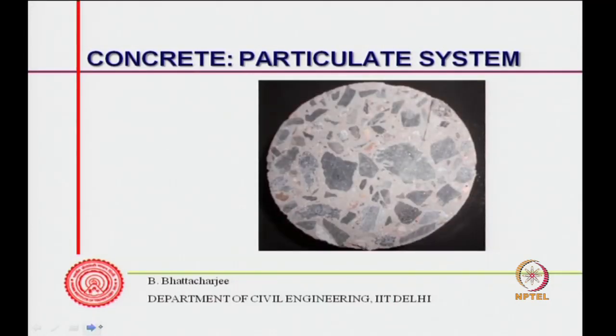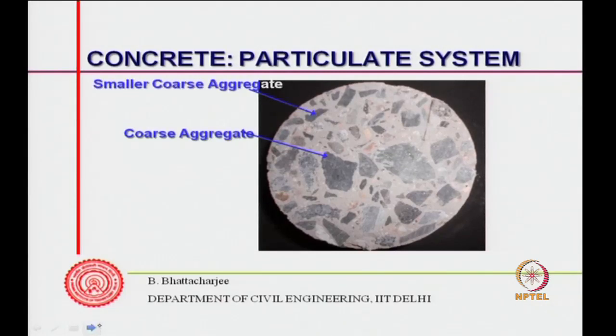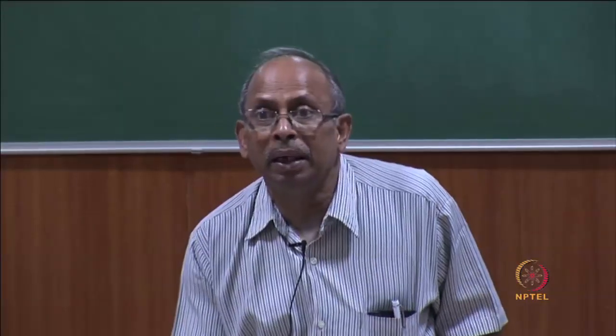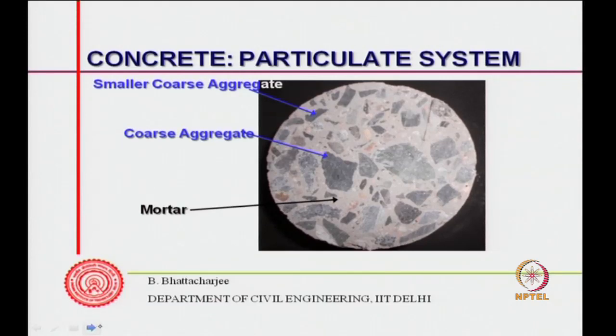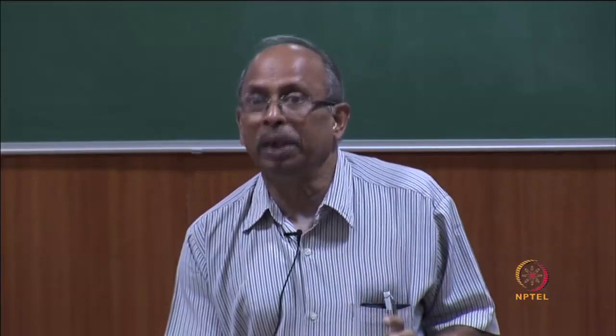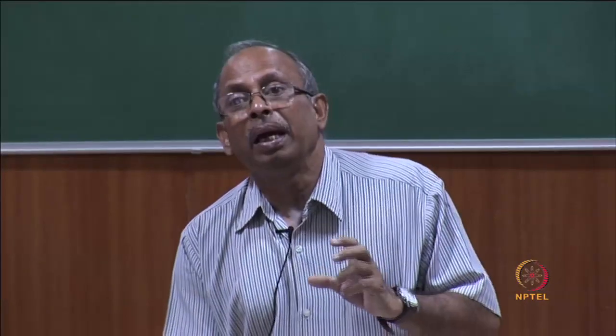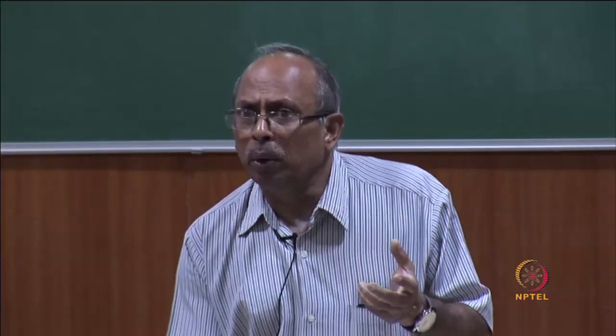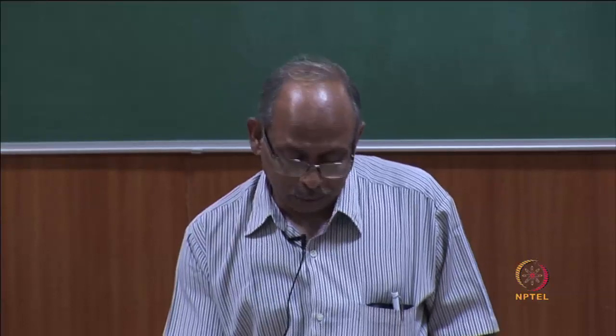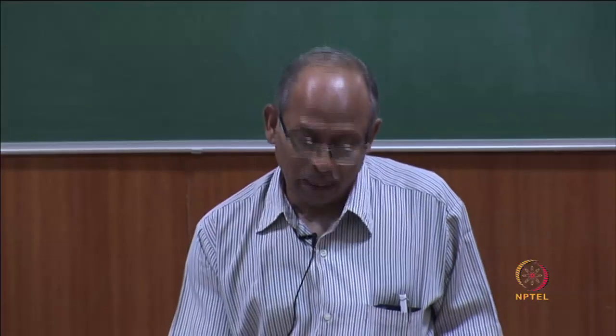So, you see in this one the larger size coarse aggregate, and the relatively finer, relatively less coarse, smaller coarse aggregates go into the interstices, and the rest is all filled with the mortar system. So, you see the packing of the particulate system is very, very important, because if the packing is good, you will require less paste. And we talked about this earlier also, and we talked about the concepts of packing density, if you recollect, from one of the earlier modules.